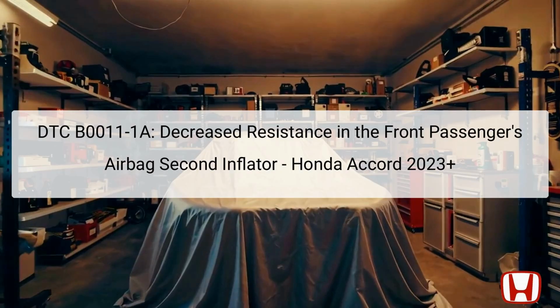The airbag system is crucial for passenger safety during a collision, and this specific error suggests a decreased resistance in the airbag inflator circuit. The airbag unit and associated wiring must operate within a specific range to ensure proper deployment during an accident. The SRS, Supplemental Restraint System, unit monitors these conditions, and when a fault is detected, it triggers this DTC stored in the system's memory.